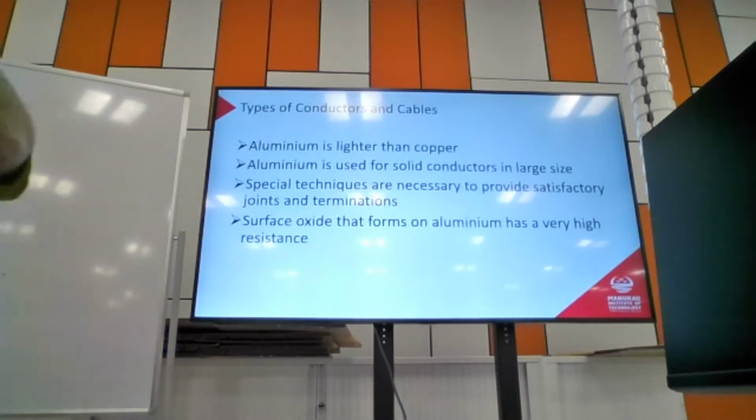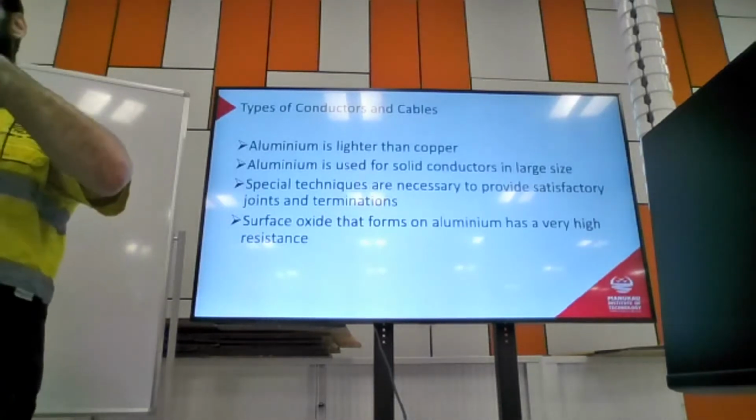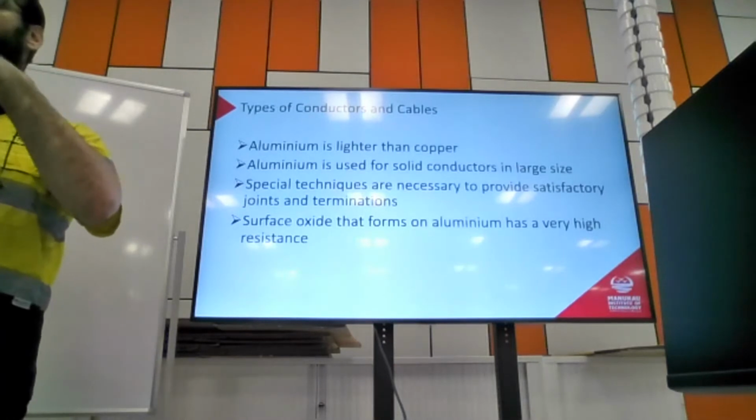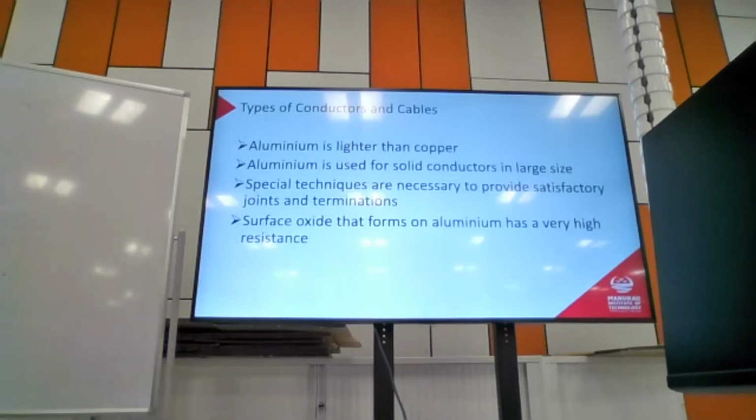So what happens is that exposed aluminium will react with oxygen in the air, and it produces an oxide layer. And that oxide layer can be quite helpful because it's really hard and it's really resistant to heat. So if you just get a torch and you melt a piece of aluminium, what you'll see is it starts to melt. The inside will melt first, and then the skin on the outside, the oxide layer, will stay unmelted. It'll stay solid. So you'll see it start to expand, and then eventually that oxide layer breaks, and then the liquid will run everywhere, which is kind of neat.